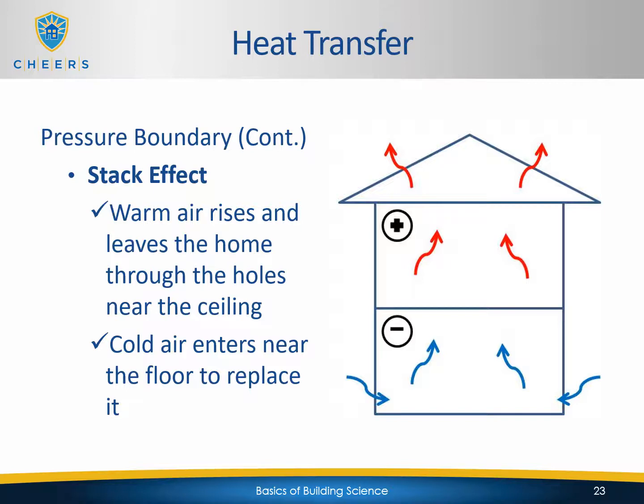But nonetheless, you could have the stack effect also be present in a single story house. Nonetheless, cold air enters the bottom of the building. We're going to have negative pressure. It rises, it pushes up, and then because the air is being pushed up to the top, you're going to have more positive pressure toward the top of the building. And that air is going to be pushed out through exfiltration points somewhere at the top of the building. And that's an example of stack effect.